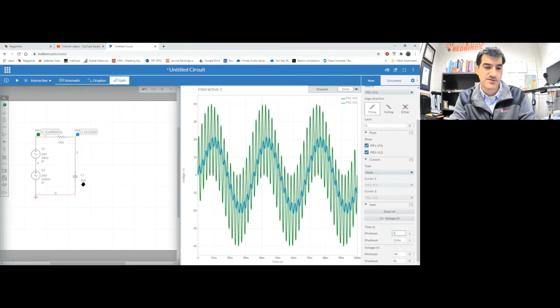So all I have to do is the same thing. 1 divided by parentheses 2 times pi times 1000, that's the resistance, times 2e negative 6, because I have a 2 microfarad capacitor. Now, it's probably not surprising since I doubled the capacitance, I have half of the cutoff frequency. So now my cutoff frequency, instead of being 160 hertz, is 80 hertz.